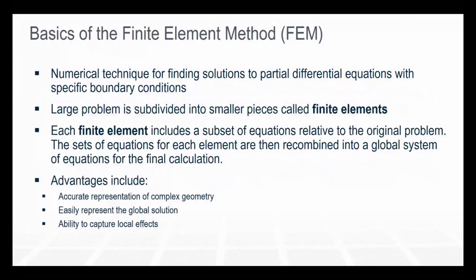Before we get into SCIA, let's talk a little bit about the basics of finite element analysis. For those who may be new to this type of analysis, basically what we're talking about is a numerical technique for finding solutions to partial differential equations within a specific set of boundary conditions. Really what we have is a large problem, in many cases large structures or something you would never attempt to do by hand, that is subdivided into smaller pieces, which we call finite elements. Each finite element includes a subset of equations relative to the original larger problem. This set of equations for each element is then recombined into a global system of equations for the final calculation. A lot of this happens in matrices and matrix techniques.